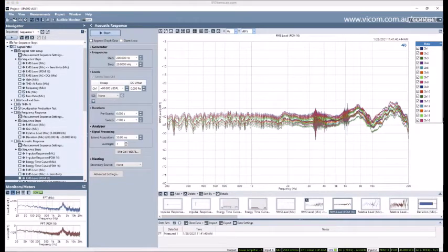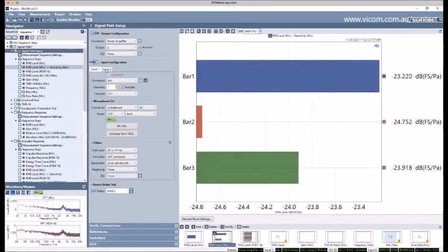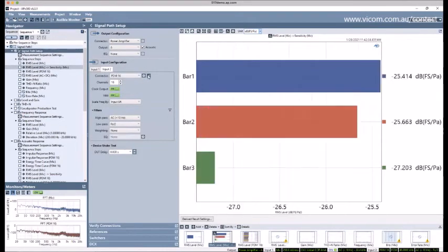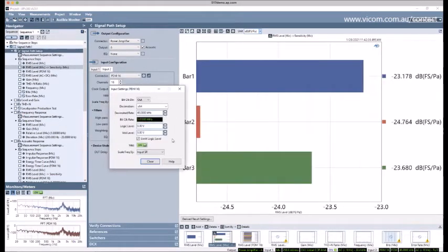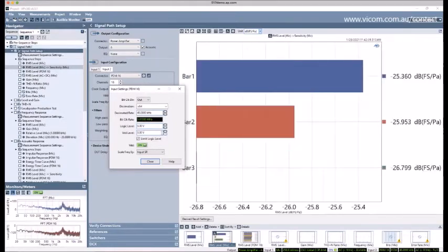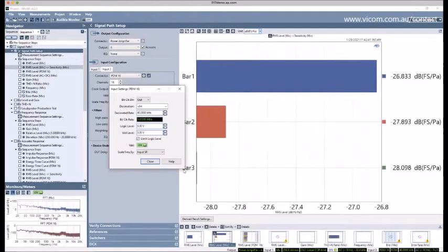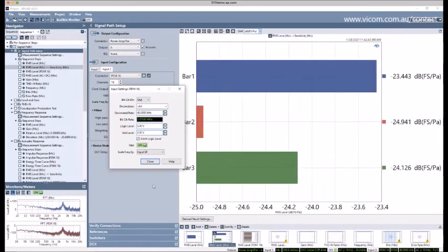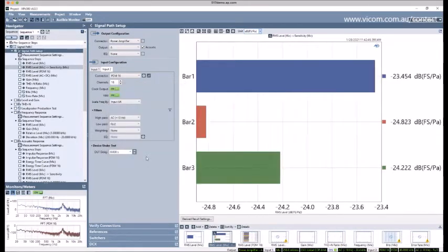Let me just quickly address a couple questions. Todd K. asks, if you change the PDM configuration, you can switch left and right channels based on the rising falling edge to resolve the microphone pairing. That is correct for our PDM module. Let me just double check here. Yeah, we did not implement the ability to swizzle the channels in software on the PDM-16 module, though that's something we may reconsider.